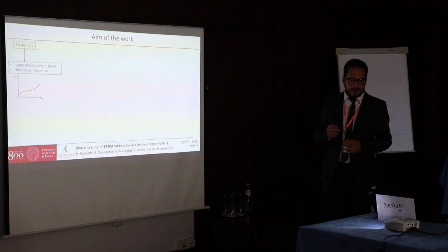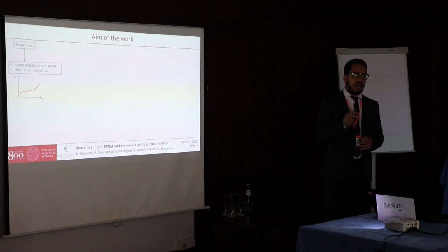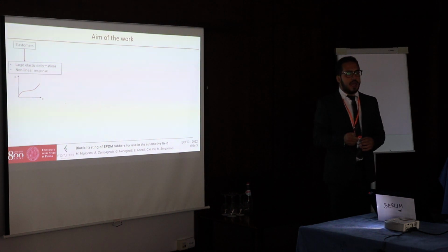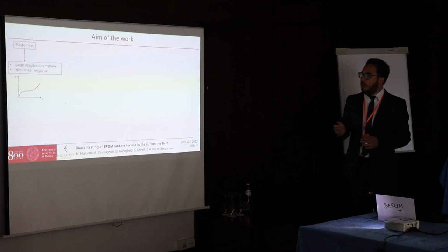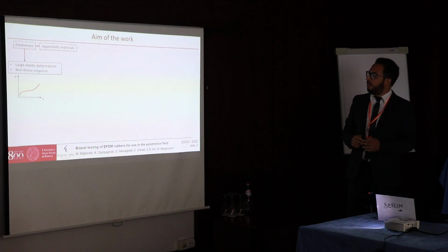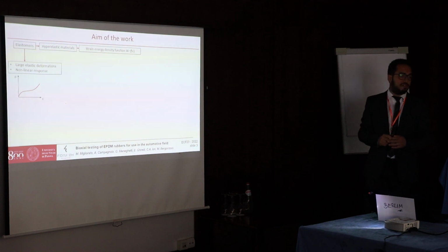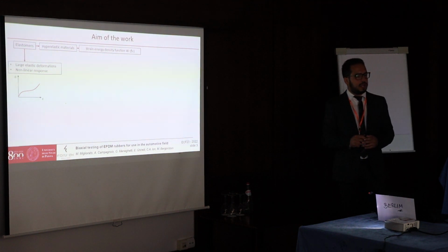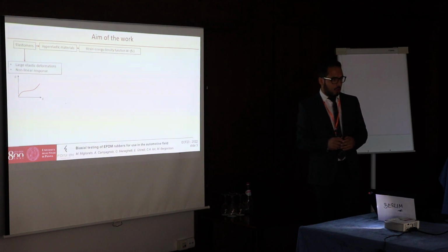Elastomers are characterized by large deformation under the action of relatively small stresses and show a non-linear stress-strain relationship. They are classified typically as hyperelastic materials, and their behavior is defined on the basis of a strain energy density function, which, when derived with respect to a strain component, provides the relevant stress component.